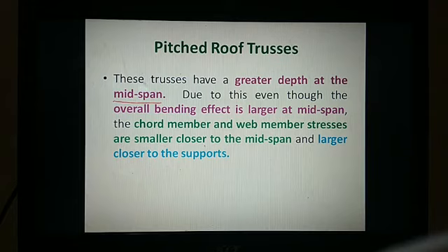So in pitched roof trusses, the depth at the center will be more to control the bending action of the complete roof truss acting as a beam. That's why the overall bending effect is larger at the mid span and the truss has more depth there.